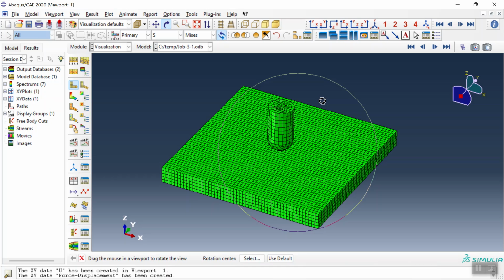When the tensile stress becomes sufficiently high, cracks begin to form. The brittle cracking model allows Abaqus to represent this behavior through a smeared crack formulation. In this approach, Abaqus does not create a physical geometric crack through the finite element. Instead, the effect of the cracking is represented at the integration point of the element through cracking strain and change in the material stiffness. You can see the example here and the schematic of the model.